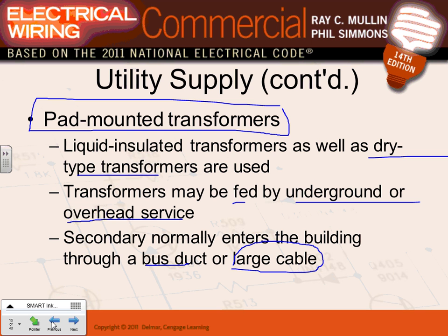It's like an extension of the panel. We use this, guys, typically if you service 2,000 amps and higher. That's a good application for it. Less than 2,000 amps, it becomes not good. You can use it, but not a good application.